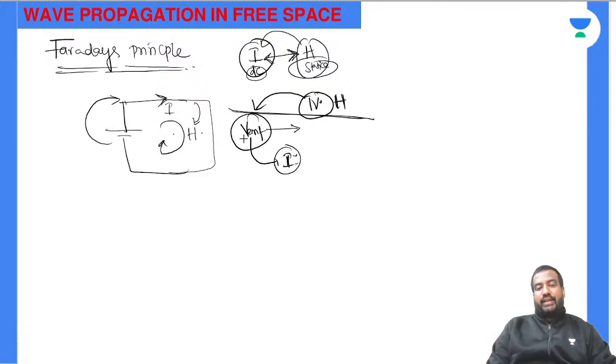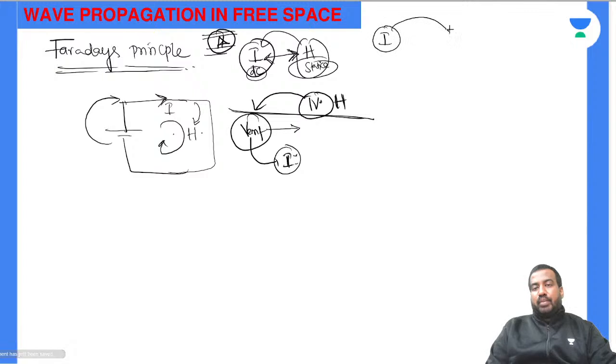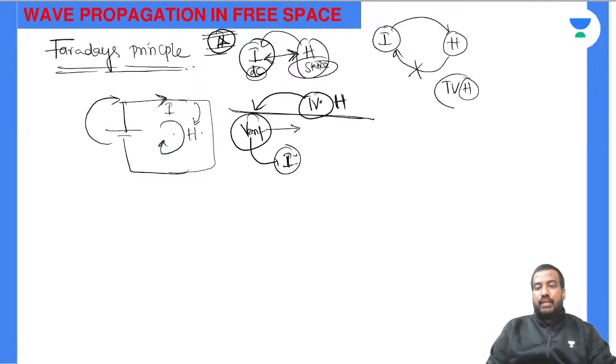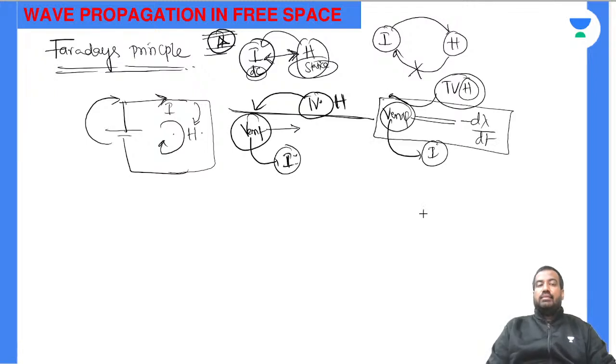We start from this point, but students should understand from this point. A DC current can produce a static magnetic field, but vice versa is not true. But a time varying magnetic field will induce an EMF within a closed path, which is responsible for the flow of current. Such induced EMF is equal to the rate of change of flux linkage. From this you get Faraday's law.